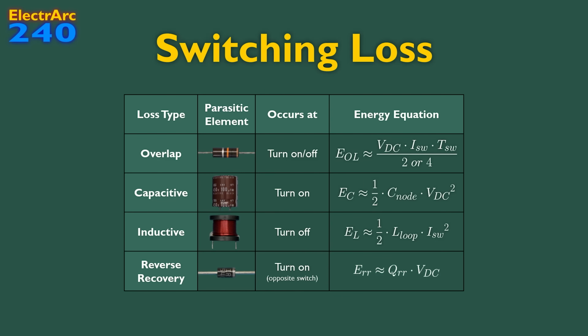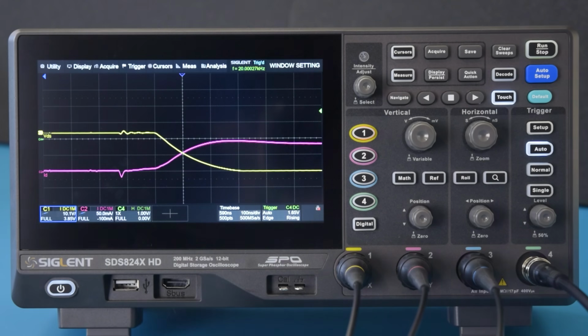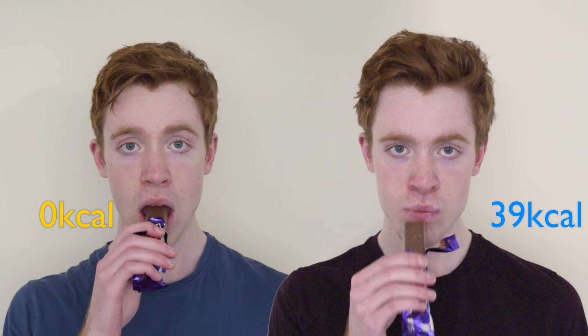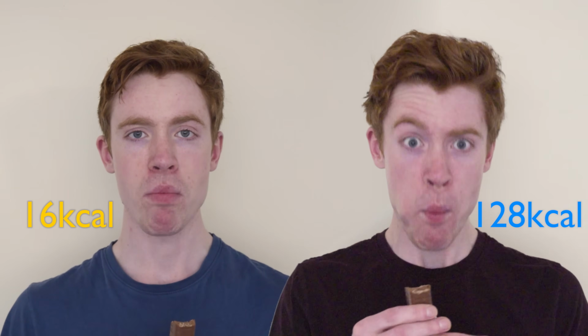The losses from the energy stored in the capacitance and inductance are easy to overlook, as they're often small relative to overlap losses. But while overlap loss can be lowered by switching faster, reducing the time between on and off, the stored energies are constant, irrespective of switching speed, so the same amount will always be dissipated. It's like eating a chocolate bar. No matter how fast you eat it, it's still got the same calories.